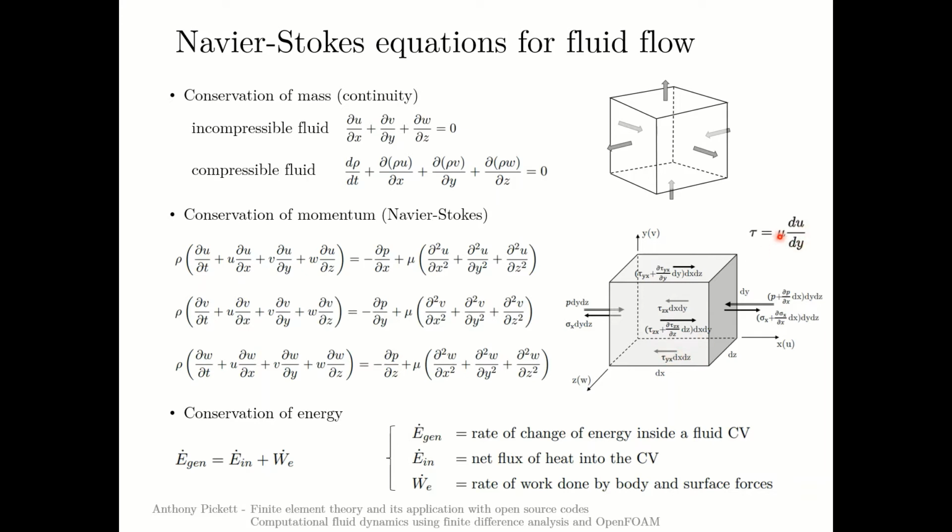Du/dy times the viscosity will give me the shear stress. So I can replace all these shear stresses on the previous slide with this relationship, and I end up with this expression here. And we have similar laws for the y direction and the z direction.